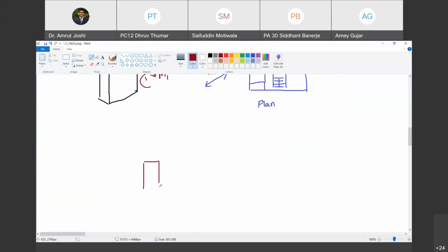This is building number 1 and this is building number 2. It is located in a crowded area and the gap between the building is delta. And imagine this building is subjected to ground motion, something like this. So earthquake occurs. I am plotting ground acceleration on y-axis and time on x-axis. So in fact, this ground moves in to and fro direction such that the acceleration signal is of this fashion. And imagine for a particular case, this building deforms in this fashion and this building also deforms in this fashion. So there is all likelihood that these two buildings are going to hit one another. Are you with me?